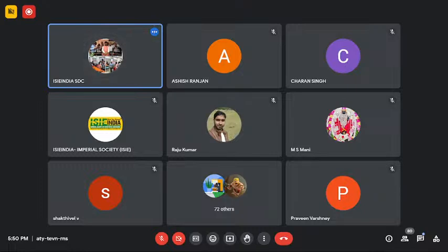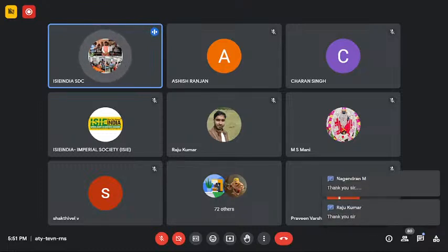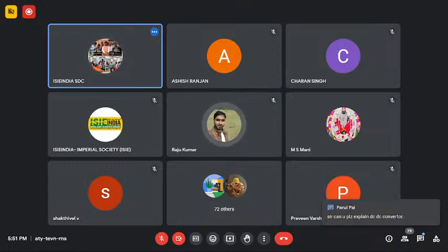So these are the main functions in the BMS. One is cell management, the cell voltage, cutoff voltage, low and high. Because it won't allow the battery cell voltage to drop, depending upon the chemistry, there is some cutoff voltage. It won't allow the battery voltage to drop below that. And same time, it won't allow the higher voltage limit also. So when the voltage level in each cell reaches a certain higher voltage limit, automatically BMS will shut down the charging process. So that is one of the functions.